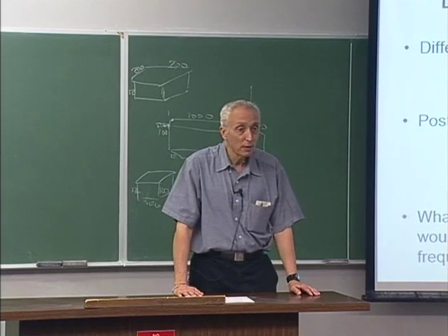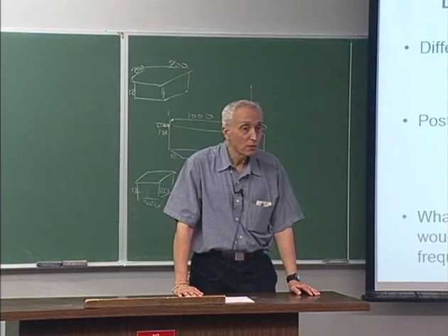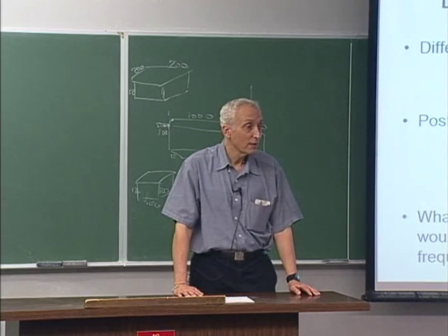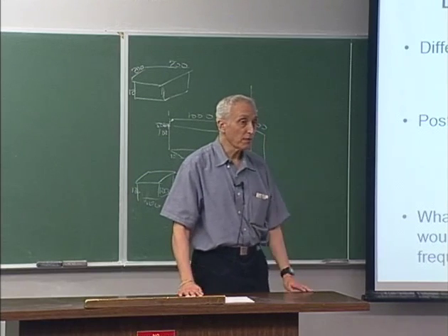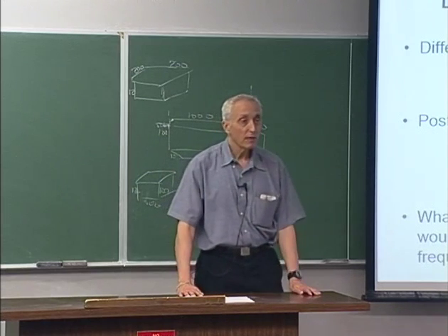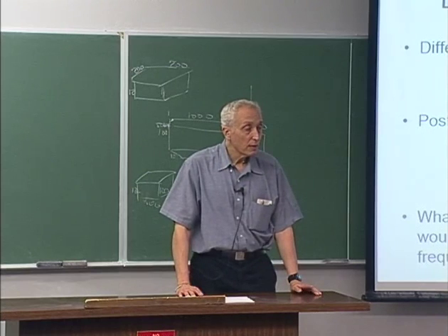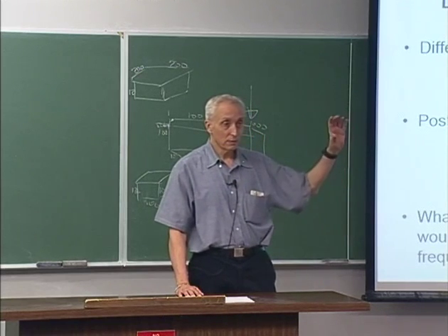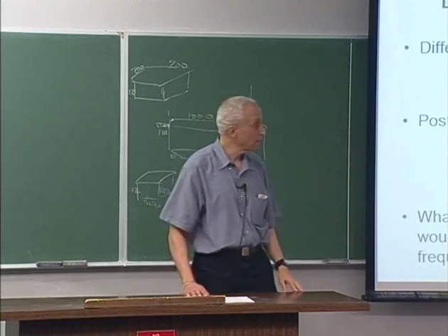What about tip and root, or free end and clamped end? Which elements in the beam contain more strain energy? The one closer to the root. Root, right. So if you want to increase the vibration frequency of a beam by making it stiffer, do it at the root and far from the neutral axis.